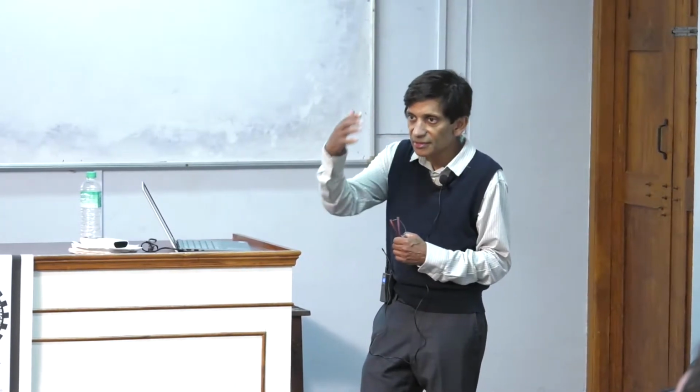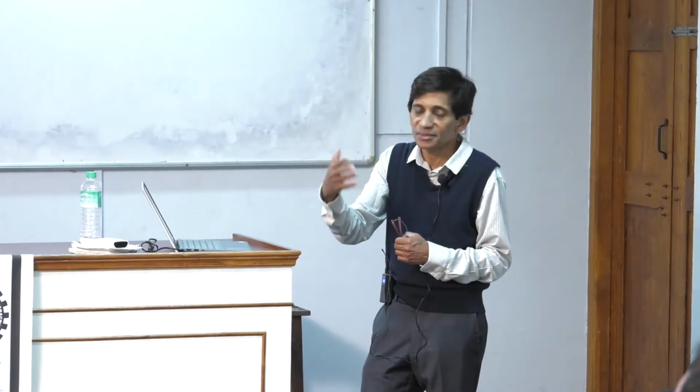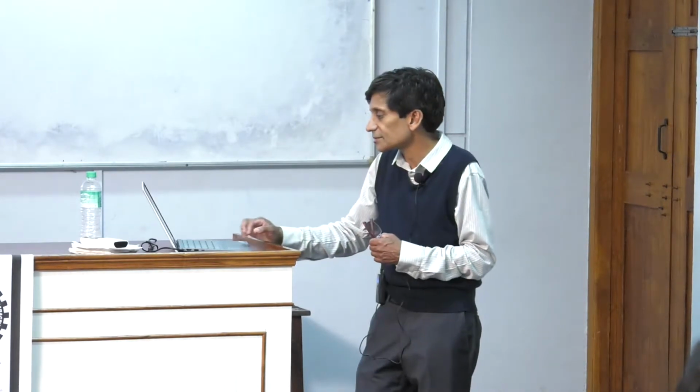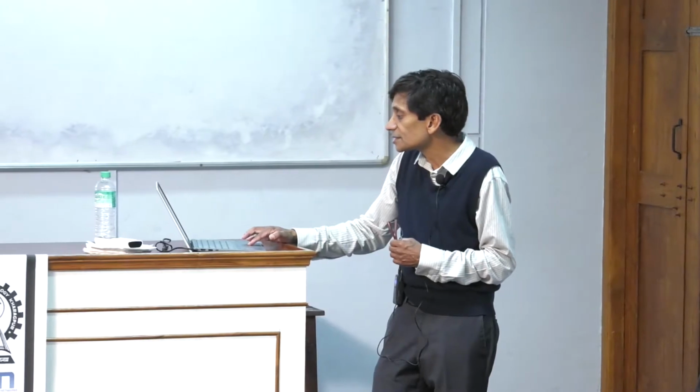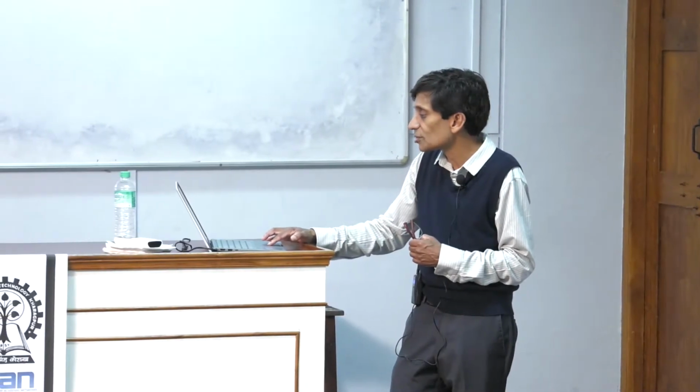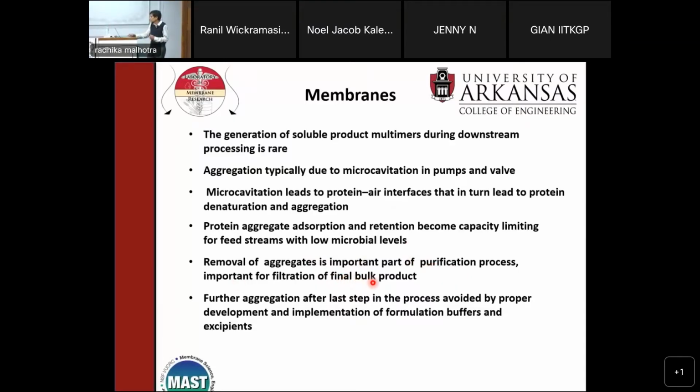That makes sense, right? So for sterile filtration, if there are not many microorganisms, and there shouldn't be, then what's going to limit capacity is going to be the presence of protein aggregates. Removal of aggregates is an important part of the purification process, important for filtration of a final bulk product. Further aggregation after the last step in the process is avoided by proper development of formulation buffers and excipients.